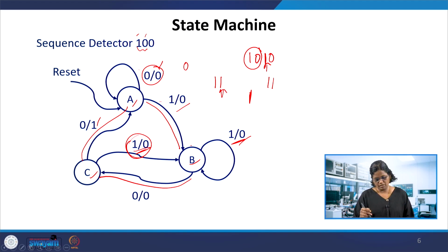When we identify the ABC for the correct pattern, deciding the breaking sequence is the harder part. If the expected bit is not received, we have to decide whether to stay in that state or go to an intermediate state where it can form a part of a sequence, or where the sequence is partly identified already. Here it's a perfect example: it stays here at 1 and then expects 0 0.